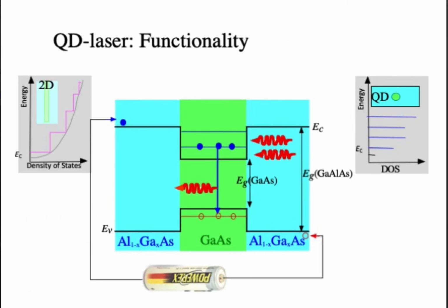Then let's just look at, simplified, how the quantum dot laser may work. We pump it electrically, so we inject electrons and holes into the semiconductor. Electrons will fall down into the quantum dot and holes will float up into the quantum dot. Thus we get many electrons and holes there, so we may have a population inversion. We get photon emissions from electrons recombining with holes. They have a relatively well-defined wavelength. As these are reflected from the edges of the piece, we get stimulated emission.